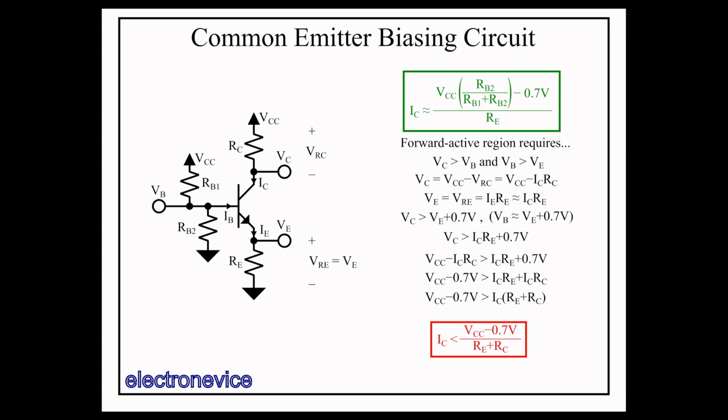I've put this equation in terms of IC rather than the parameters above in our IC equation because a target IC is usually decided upon when beginning or iterating on an amplifier design, and so you generally design the components around a target value for IC, so it is usually easier to think about subsequent parameters in terms of IC. So now that we have our collector current, and have ensured the transistor is biased into the forward active region, we can move on to the small signal circuit, which is the more interesting portion of the common emitter circuit.